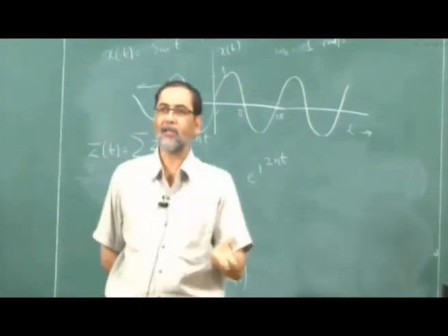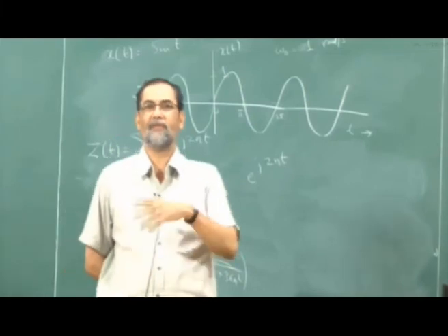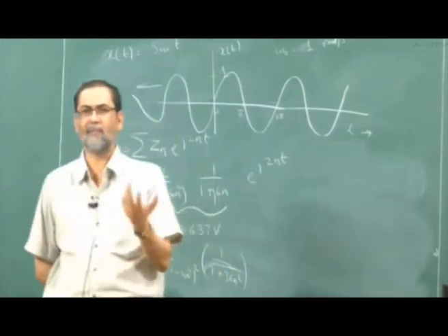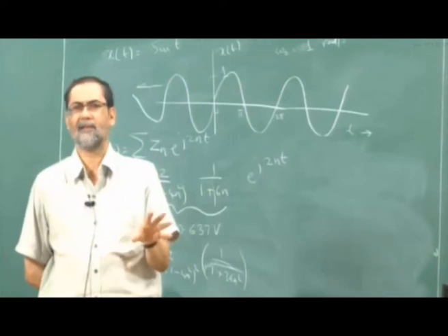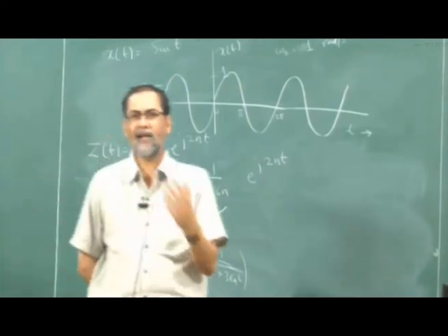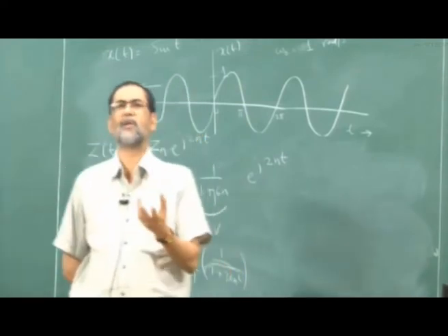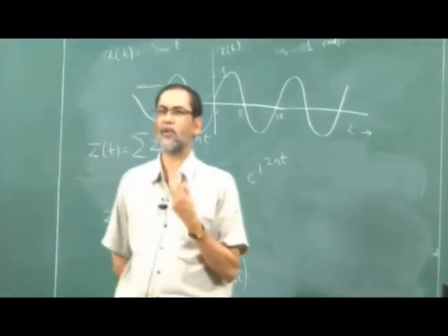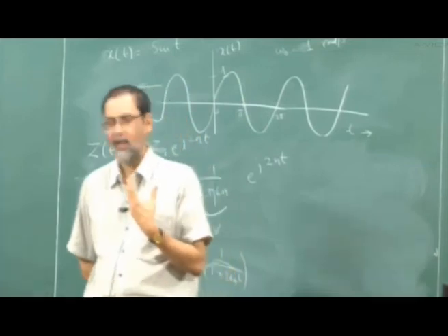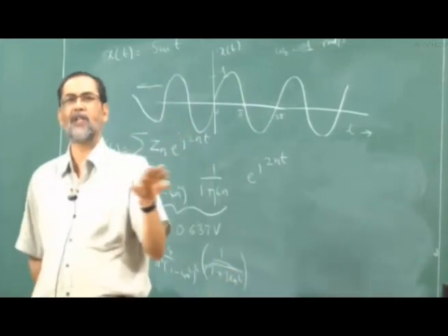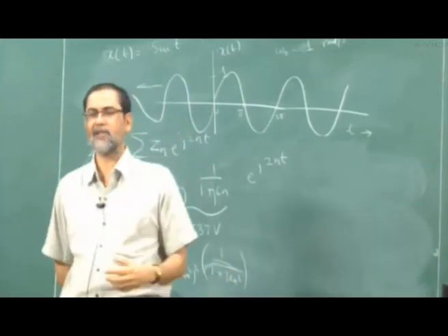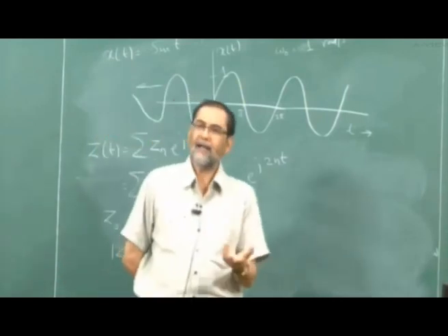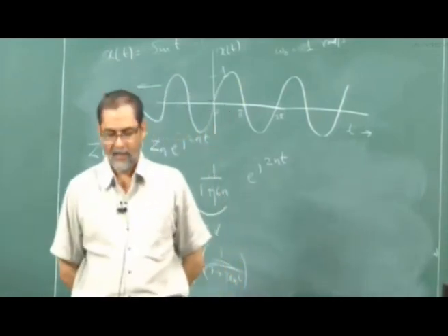You multiply cos and cos, sum and difference frequencies show up, and it's a big mess. Whereas manipulation with exponential is quite easy. So there are two advantages of exponential form: direct application of LTI as eigenfunctions and easier manipulation.